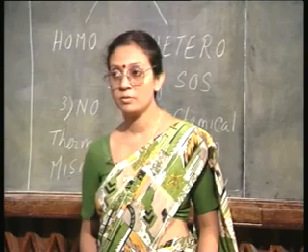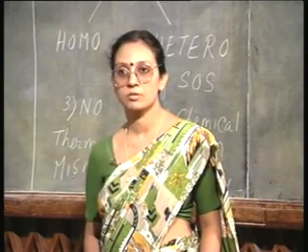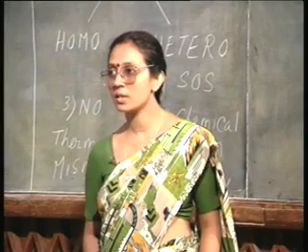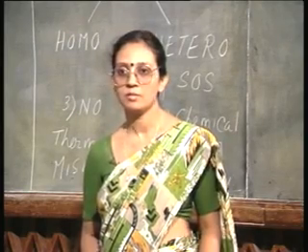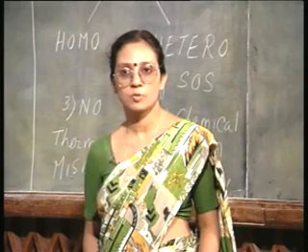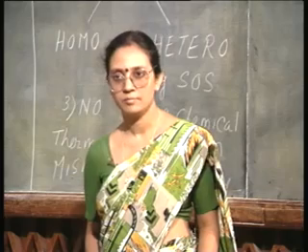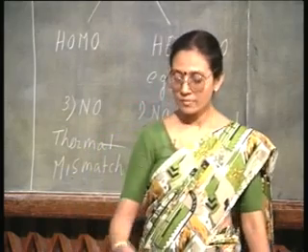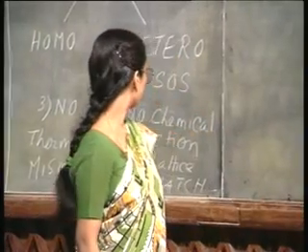One major problem with gallium arsenide technology is cost. So, if you can use the silicon bulk crystal and grow a thin layer of gallium arsenide on top of that, you have circumvented the cost problem. So, even that is possible to a certain extent today. So, heteroepitaxy is again a very interesting point.